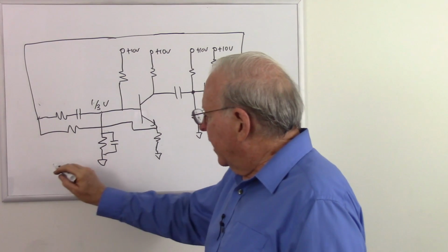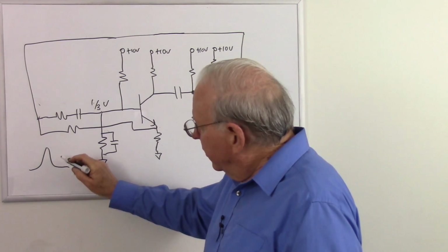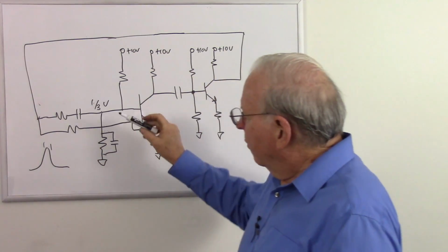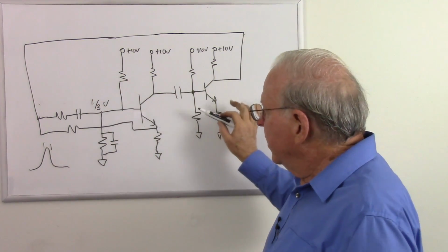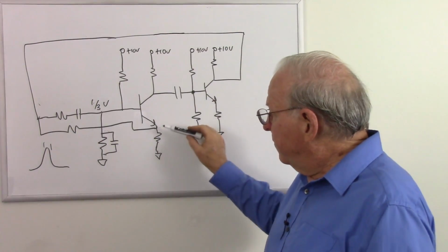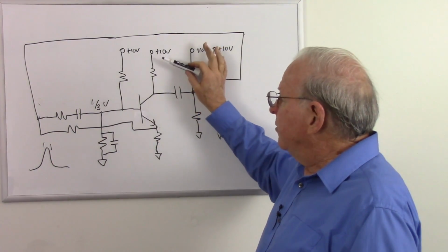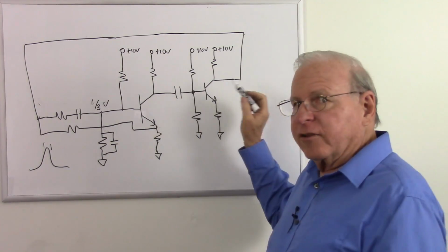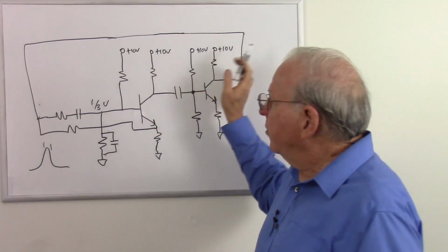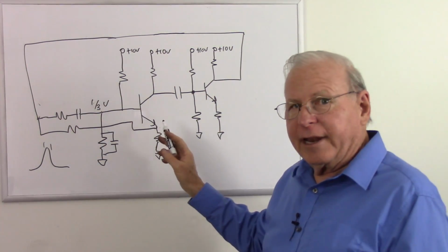So there we have it. That acts as a bandpass filter that has a fairly high Q, so very narrow bandwidth, so only frequencies very close to our cutoff frequency can make it into the amplifier. So even though it's very fiddly to get the gain just right, if it gets close to saturation, what that's going to do, it's going to introduce odd harmonics. Those harmonics are frequencies above our desired frequency. They come through here, they will not make it through this filter, and so they don't get amplified.